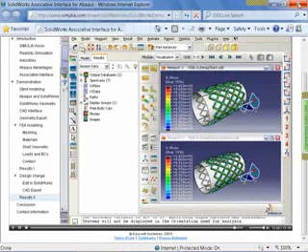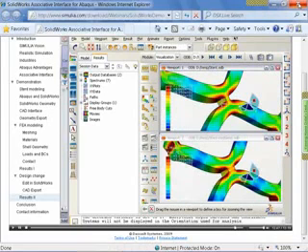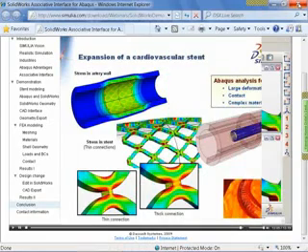With the viewports linked, I can synchronize the view of both viewports and zoom in on the region of the design change. Now we can see that increasing the width of the connection between the stent loops does not have a significant effect on the stress around the connection. If anything, the stresses in this region are slightly higher after the design modification.